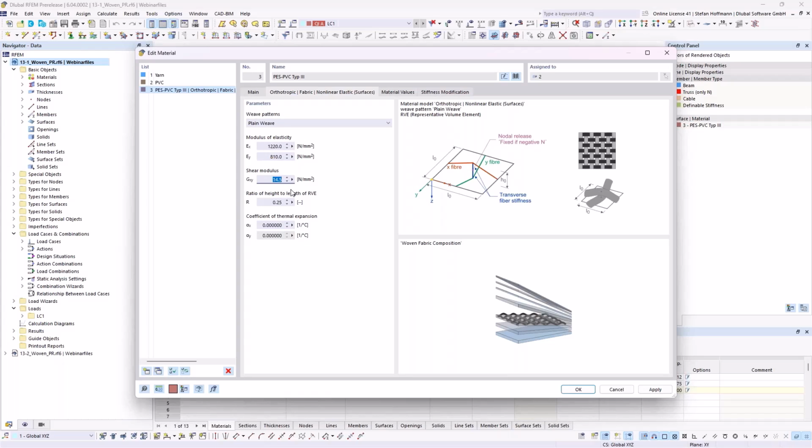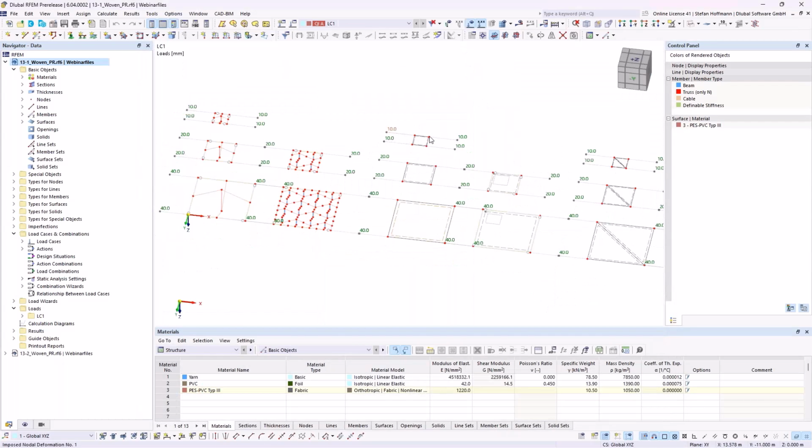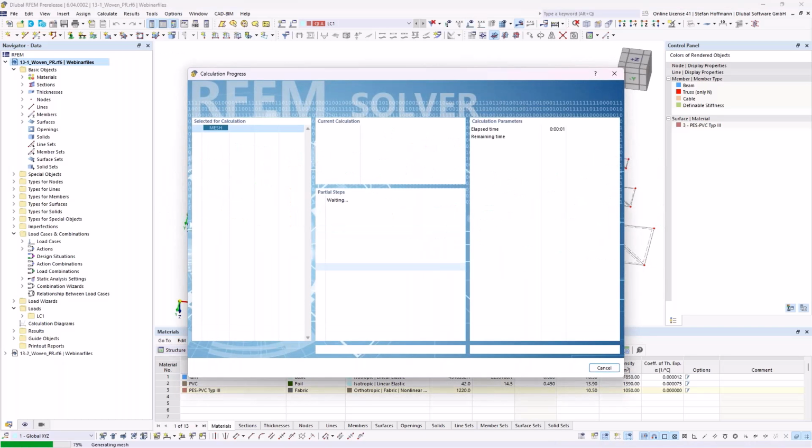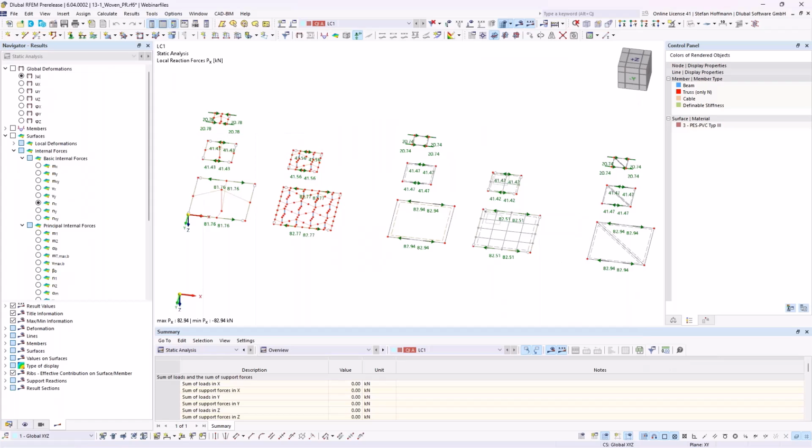You can define a coating if you want to, and you can define a ratio of this. So this one is an example to test, if we have now support movement, what results can be achieved with the nonlinear material model compared to the element which is in the background. It will not fully match, depending, of course, on the type of convergence where you then will set your equilibrium. But you can maybe see in the support forces we are close to the reasonable results.